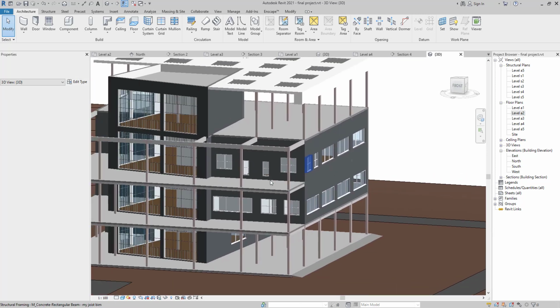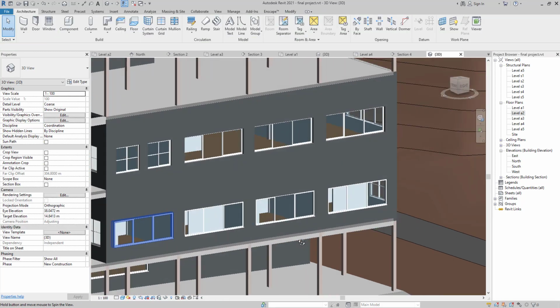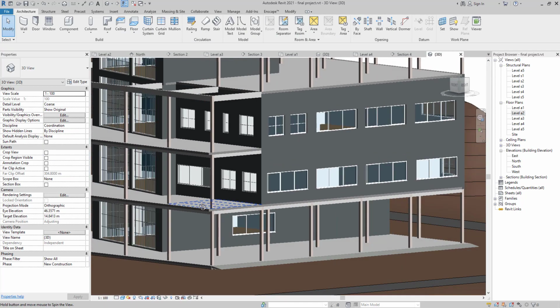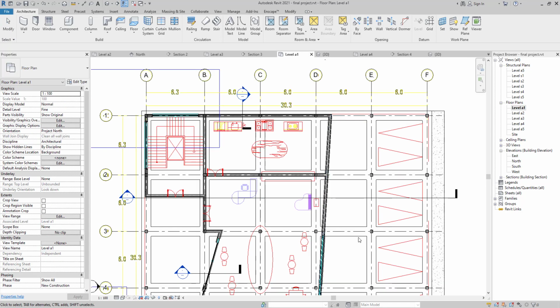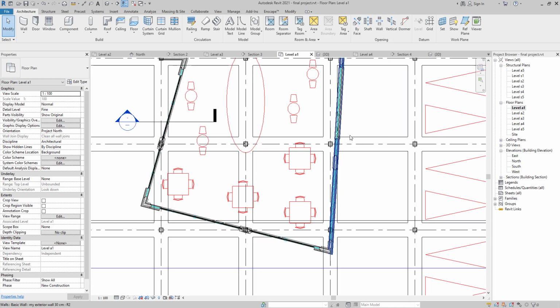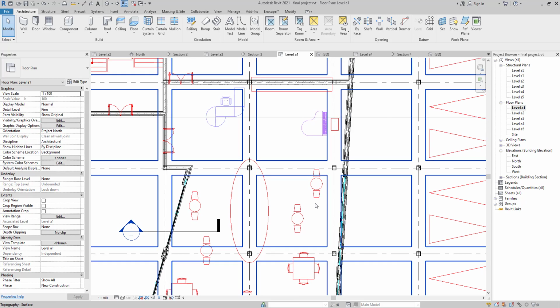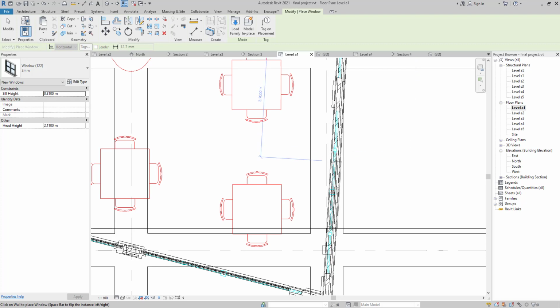And here we need to change the location of this to 890, and we already set our window. We don't have any window on the ground floor anymore, I think, because we just have 2 windows. One is here, one is here, but we didn't place this one, so we will go to WM 2 meter window, and we are going to place it here, because the 5 meter wasn't a suitable window for this location.